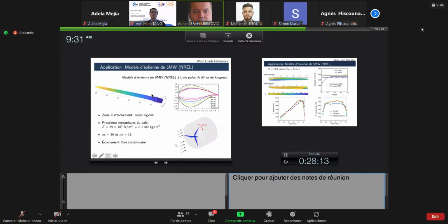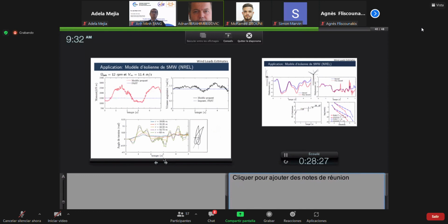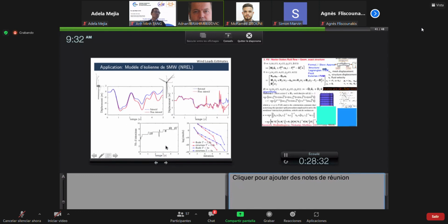And basically, here we suggested that this can really give some very interesting results, especially if you have this kind of total force applied to the particular wind turbine, which serves to design. We compare that with more simplified methods and so on and so forth. And you can see that basically this computation could be quite interesting as we go along. There's interest in really doing implicit fluid structure interaction. In other words, that you really try to converge, because then you improve your results as opposed to a non-iterative method.